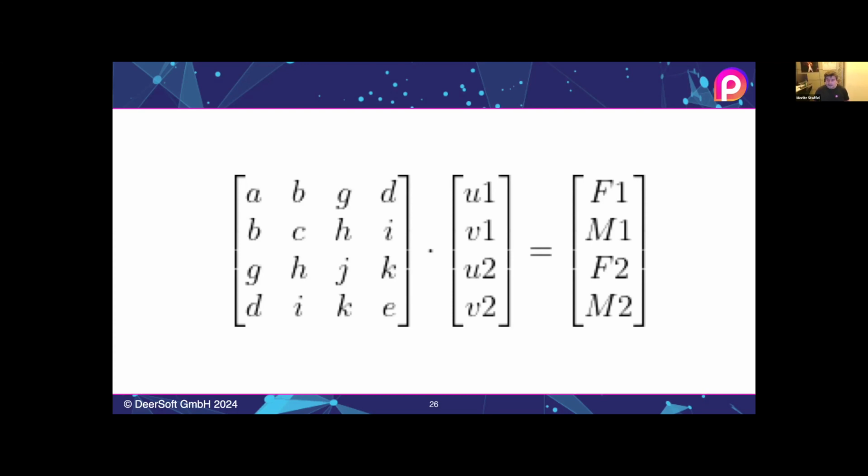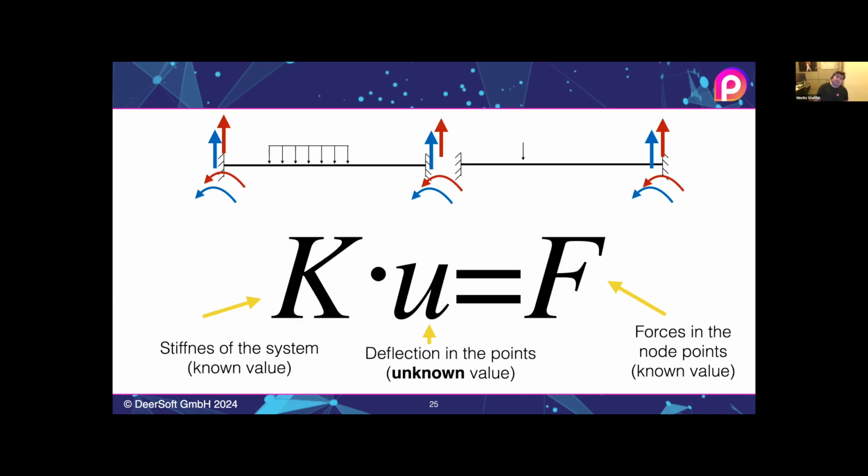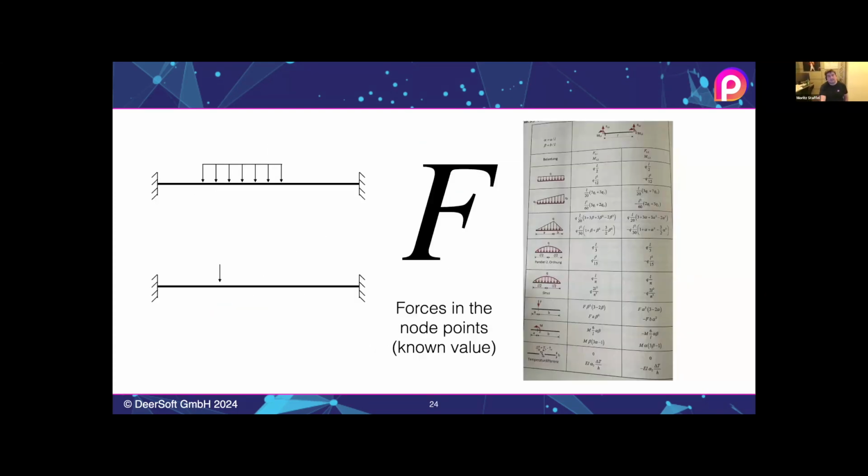The interesting part of this is that you're not actually calculating forces or reaction forces with the FEA calculation method that we are using, but the actual resulting deflections that this kind of system is making. So the important part that you need to know is that all the tables that you know from your hand calculation are part of the nodal force vector in here.